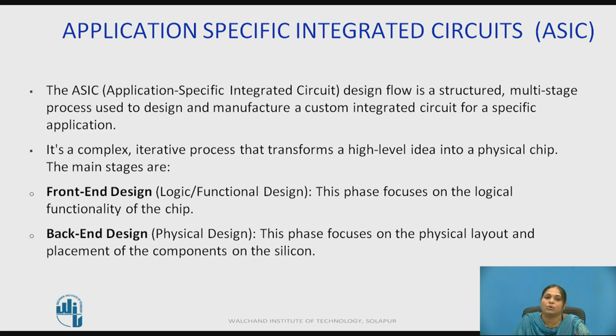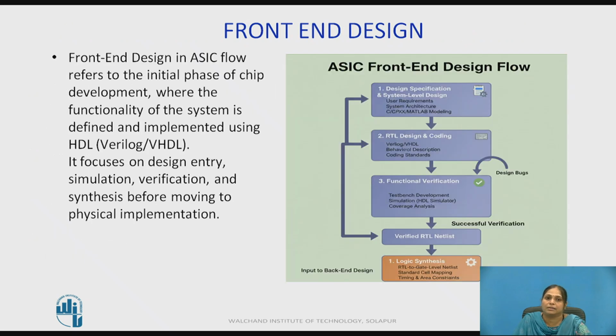The first phase, front end design, focuses on the logical functionality of the chip. Back end design focuses on the physical layout and placement of the components on the silicon. Front end design in the ASIC design flow refers to the initial phase of chip development, where the functionality of the system is defined and implemented using HDL languages like Verilog, VHDL, and System Verilog. It mainly focuses on design entry, simulation, verification, and synthesis before moving to the physical implementation.